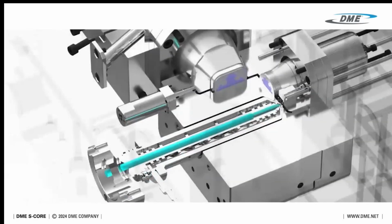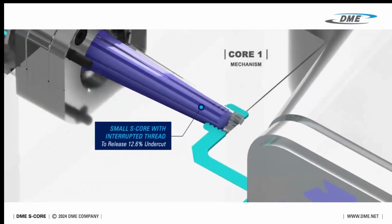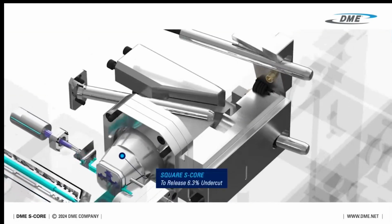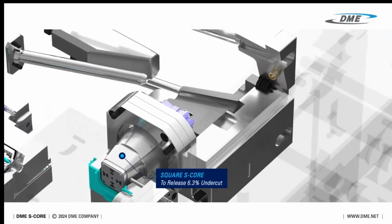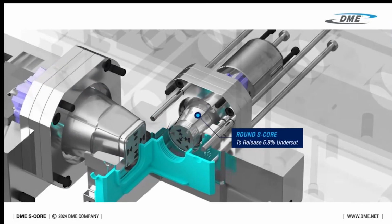First, plastic is injected into the mold, forming the part shape. Before the parting line opens, the 6 mm S-core collapses, releasing the undercut. Next, the parting line opens, causing the square S-core to collapse and retract from the part. Finally, the floating B-plate collapses the core, and the ejector pins push the part out.